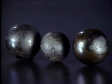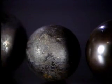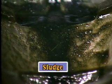More severe oxidation produces carbon deposits. Both varnish and carbon deposits can greatly increase friction on bearings and other machine parts and keep them from operating freely. Carbon deposits can also collect in lubricants and form sludge. Sludge can clog lubricant pathways in machinery and keep the lubricant from getting to where it's needed.